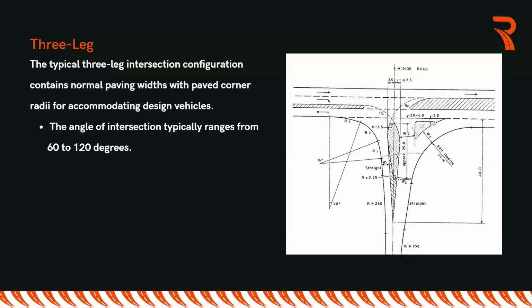The best scenario is going to give you an angle that is around 90 degrees. If you get your intersection at 90 degrees, that is good. What this is telling you is if you are doing the design of an intersection, it will be prudent for you to start with the intersection first, figure out the alignment and how the legs will look before even you go to do the horizontal alignment ahead for the entire road section.